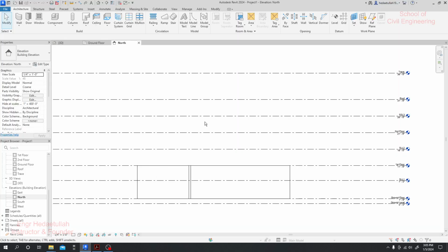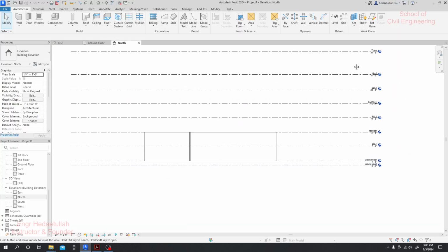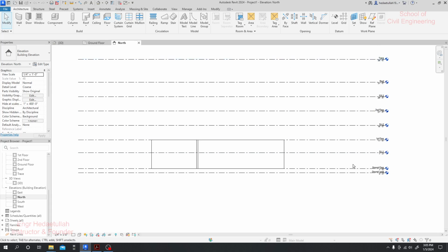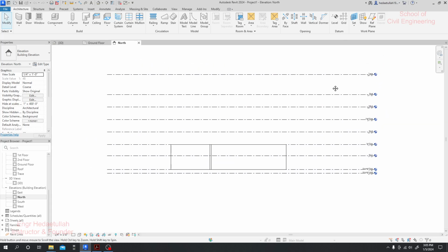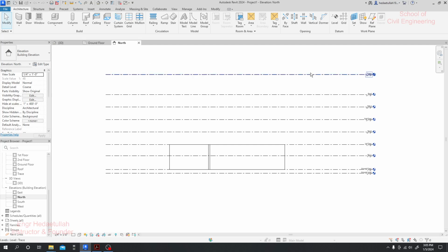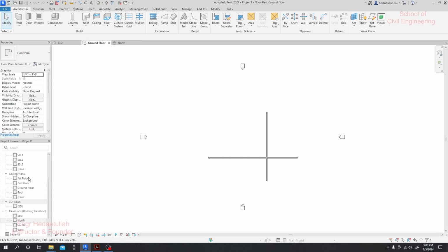So if I just go to the Revit software, in our previous lecture I created the levels. If you're new here, you can watch our previous lecture; the link is given in the description, or you can go to our playlist. Now I'll go to our ground floor. Must remember, we will not create our floor plan in the ceiling plan. We'll create our plan in the floor plan. So I'll double click here for the ground floor, and here we'll get our ground floor level.